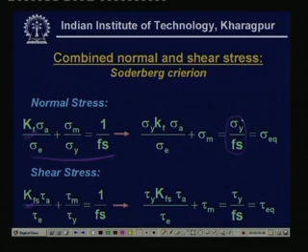The important point is that sigma yield point by factor of safety can be called simply an allowable stress or the design stress. So, one can conclude that this entire expression, which is equivalent to the design stress, will be nothing but a sigma equivalent. So, what is the idea?